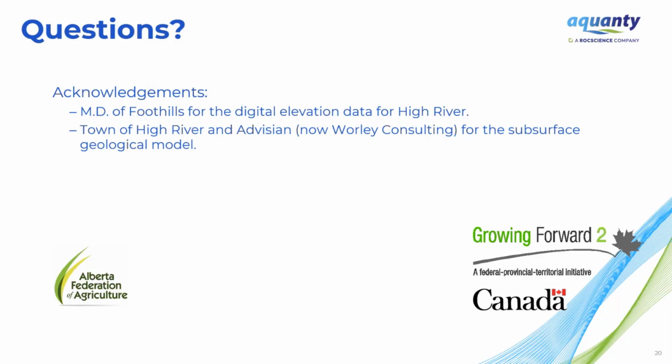I'll also comment quickly that HydroGeoSphere does have some native winter processes, snow melt, and a snow melt boundary condition, which was mentioned already in the questions. There is a native snow accumulation and snow melt boundary condition, but typically the liquid water flux data would be prepared offline. The snow melt boundary condition does tend to increase model runtimes as well, so it's generally faster to do a bit of pre-processing of your liquid water flux data beforehand, and then just apply that directly to the HGS model.